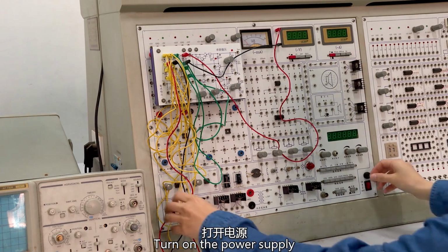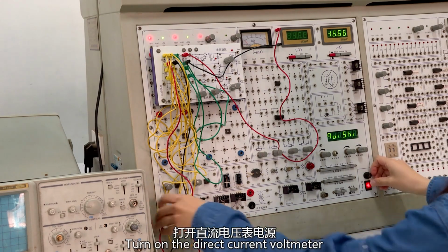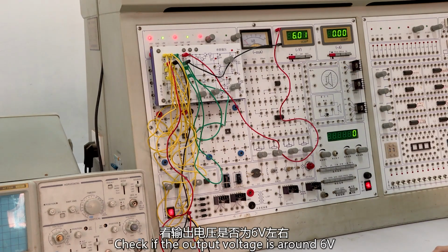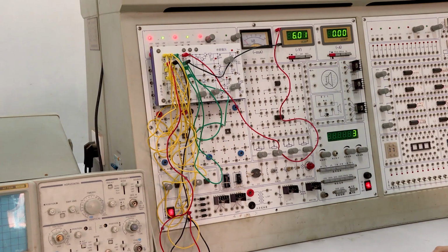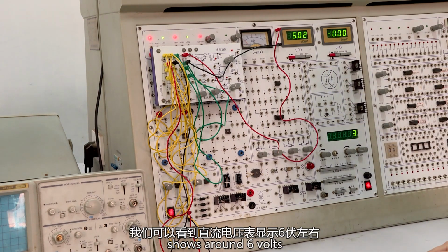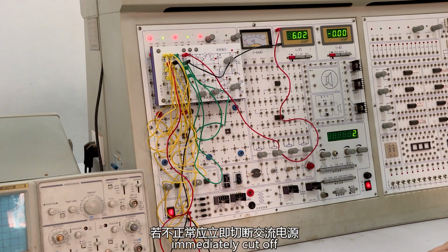Turn on the power supply. Turn on the direct current voltmeter. Check if the output voltage is around 6 volts. We can see that the direct current voltmeter shows around 6 volts. If not normal, immediately cut off the alternating current power supply.